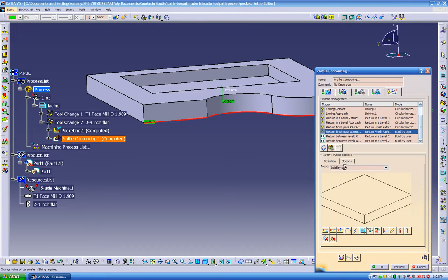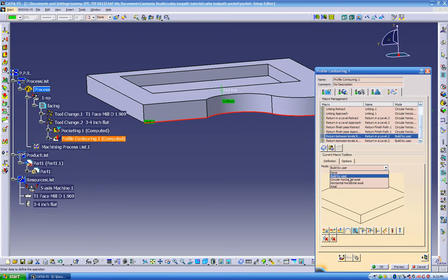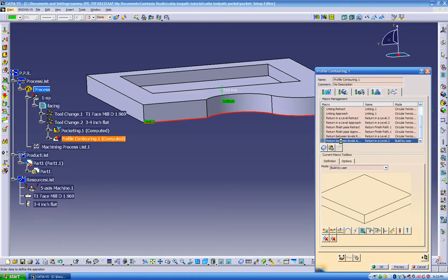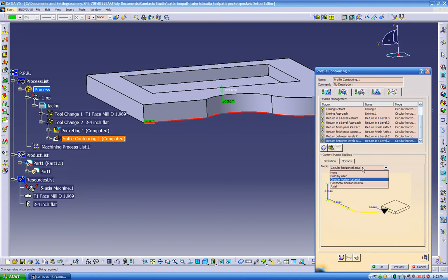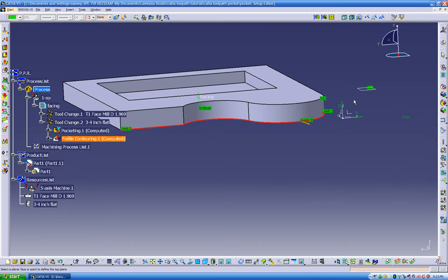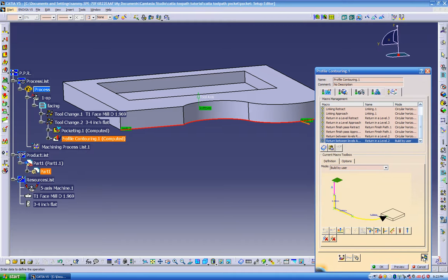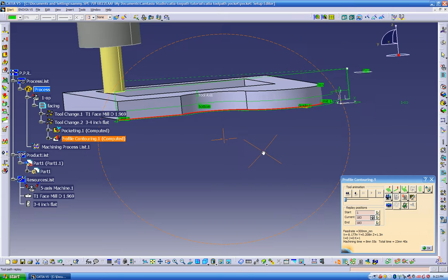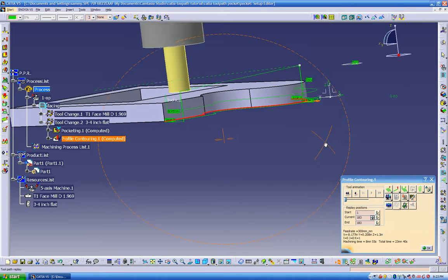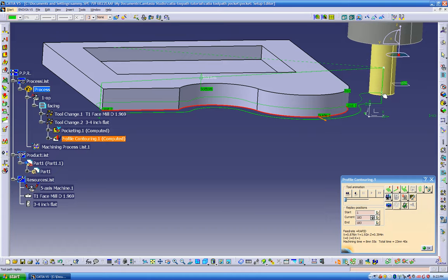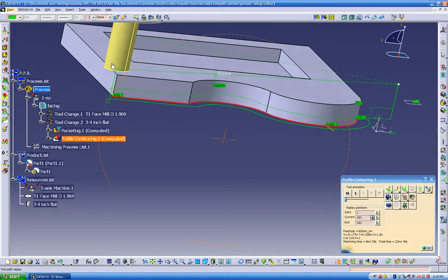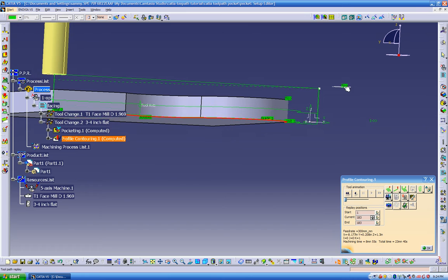I already got used to it. Okay, this is the last one. Okay, it's activated. And also we can add planes to these guys. You can go back, build by user, click on the plane, select your plane, and also you can do this. So we can bring your tool all the way to the top. So see right now how nice it looks. Every little pass leads outside, come back in, it goes all the way to the top, which is this plane that we selected.